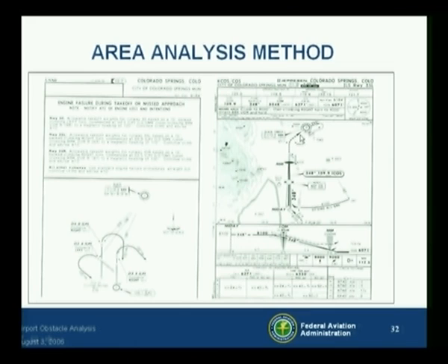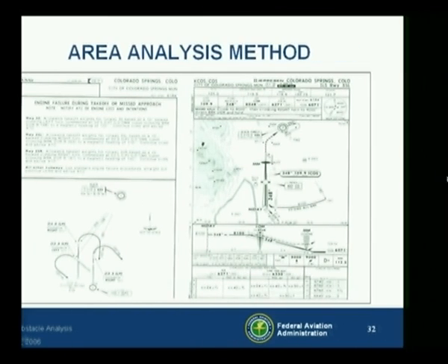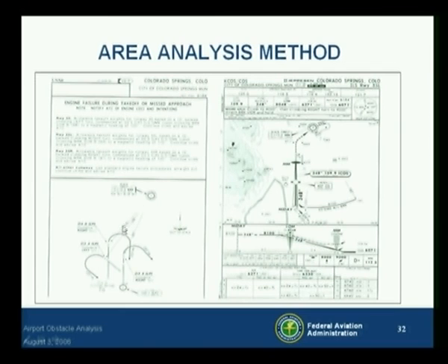So the airline has developed something called an engine out procedure, which is accepted by the POI. That beauty's right over here. For 35 left, and we're looking at the diagram in the center here that has this right turn. It says allowable takeoff weights for runway 35 left are based on a 15-degree banked climbing right turn commenced at 5 DME off the ILS localizer upon crossing the Black Forest 203 radial, which is this little radial right there. Then you continue on a right turn to 170 degrees